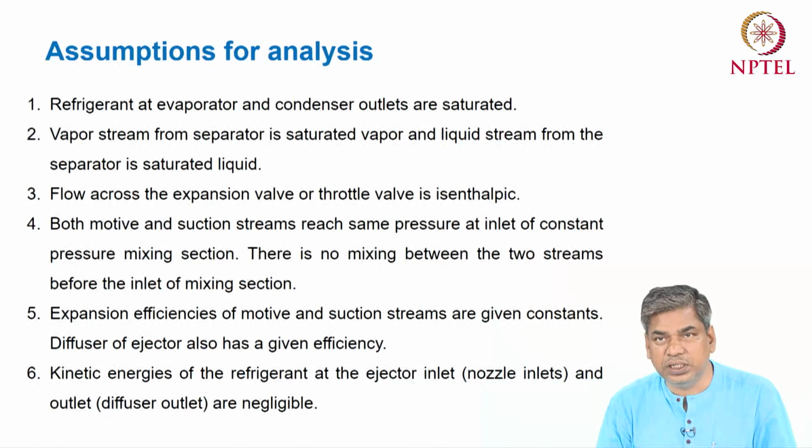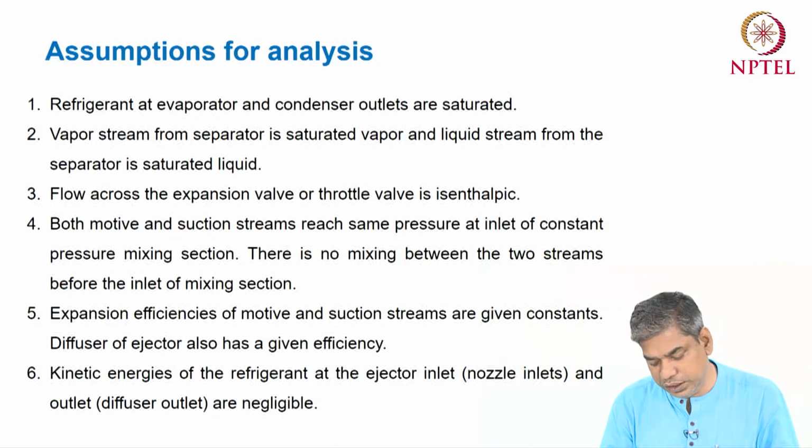Similarly, the expansion efficiencies of the motive nozzle and suction stream are given as constant, the diffuser of the ejector also has a given efficiency, and the kinetic energy of the refrigerant at the inlet and the outlet of the ejector is negligible.